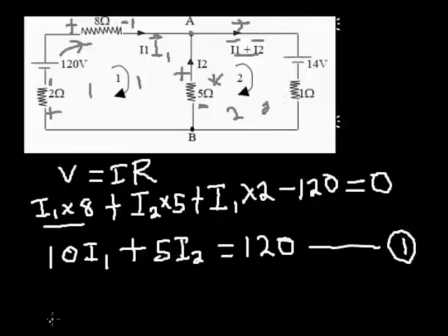So the source now, that will be plus 14. Then if I go to the next resistor, that's going to be minus, that's 1 ohm. Remember, the current passing through the loop is I1 plus I2. So that's going to give me 1 multiplied by the current, or better still, the current multiplied by the resistor, still the same thing.